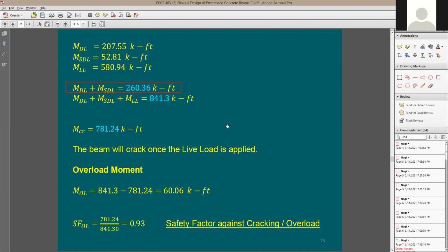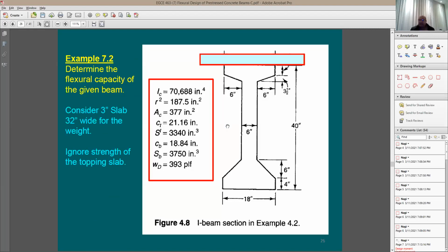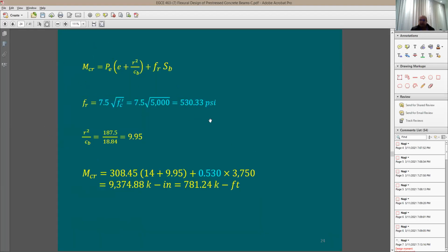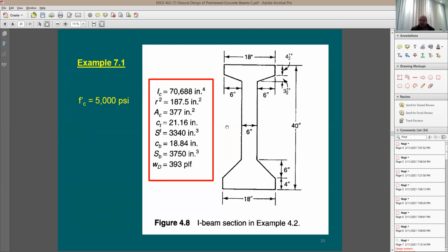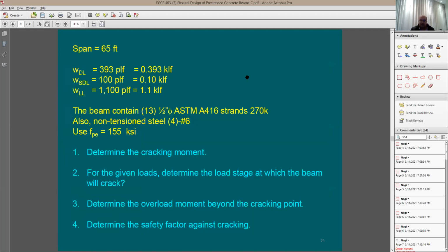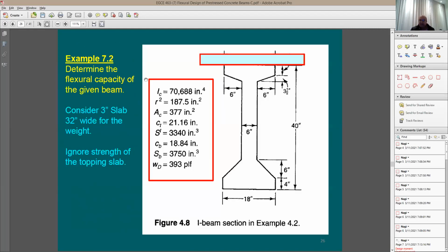Okay, thank you. All right, second example. Well, it seems to be the same beam. So first we studied just this beam. I'm going to take this and put some concrete topping, because usually these pre-stressed beams, after you install them in place, you put some reinforcing in the top and then put some concrete topping. That's exactly what happened.